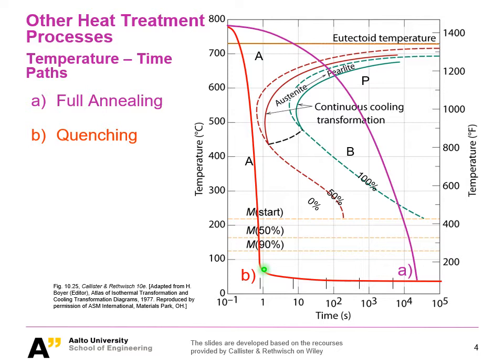But it is a phase which is not in equilibrium, right? Probably some of you might ask why it's not BCC, why it has to be BCT. You need to recall that carbon has a certain amount of solubility in the alpha phase, the BCC alpha ferrite phase, and it is not possible to have them just diffuse into a BCC phase.